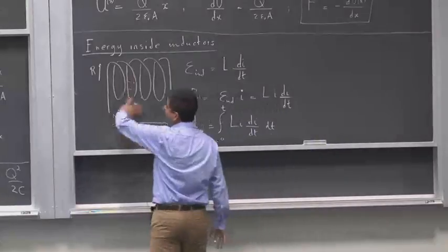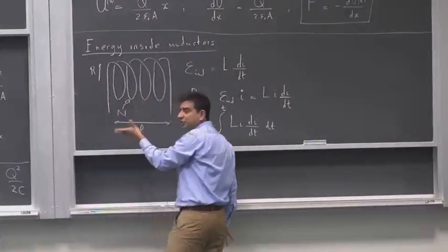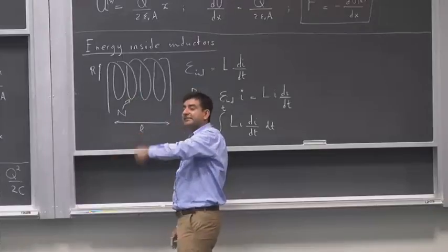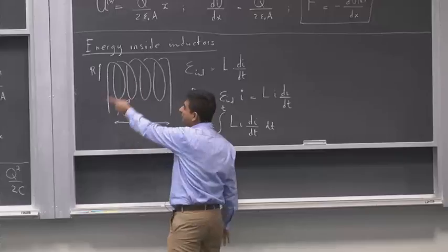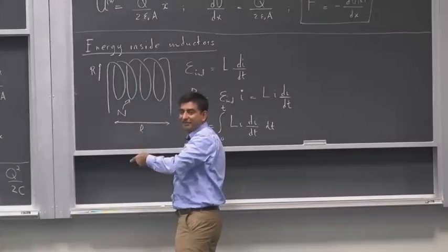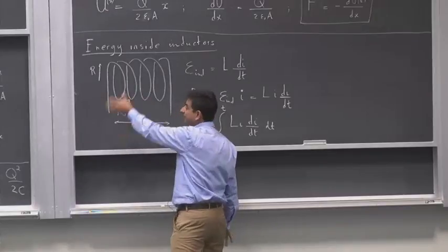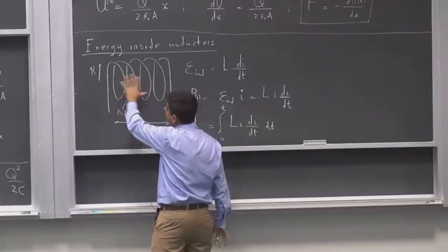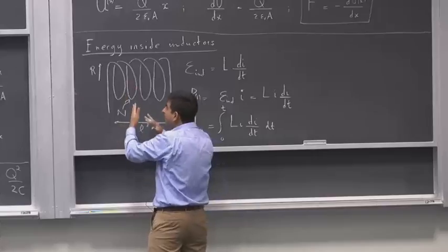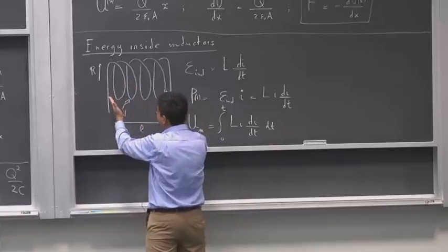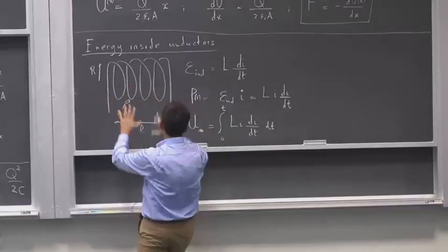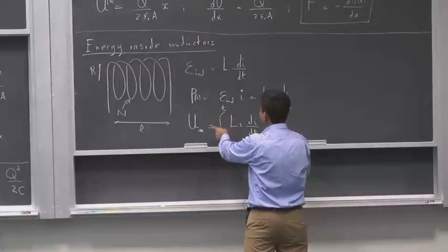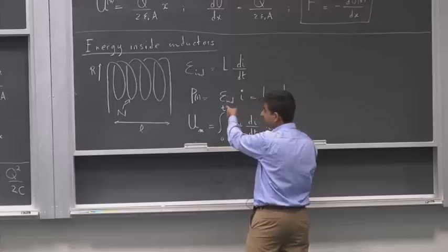So once a current flows, this inductor is not heating up, it doesn't have any resistance, that's our assumption. So that energy is going in somewhere, because a changing current has a magnetic field. If the current changes, the magnetic field inside changes as well. So a magnetic field is being produced, and that energy must go somewhere. That's going into the magnetic field. And how much energy is being delivered to this inductor? That's given by this expression. This is just P dt integrated from 0 to t.